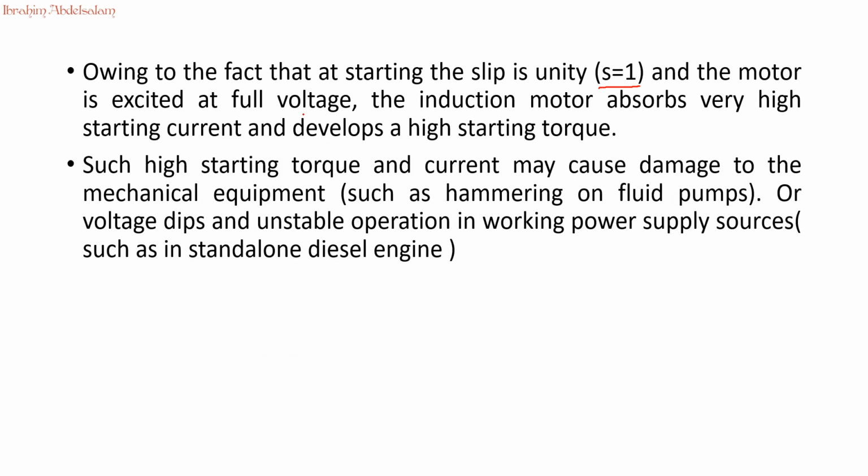This suddenly high starting current has two main side effects: on mechanical equipment, such as hammering on fluid pumps, or on the electrical utility. It can cause voltage dips and unstable operation in weak power sources.